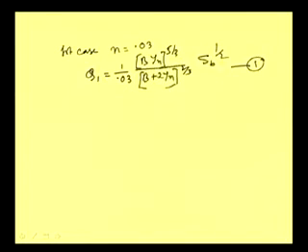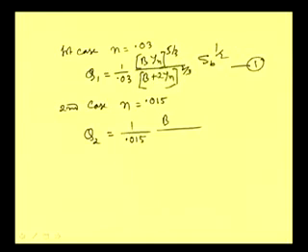Then in the second case, when n is improved, that is we are having concrete lining, then we can have Q2. We are having a different discharge, with 1 by 0.015, and of course the section of the channel remains the same. So, B yn to the power 5 by 3 and B plus twice yn to the power 2 by 3. That part is not changing. Then S to the power half. This is equation 2.